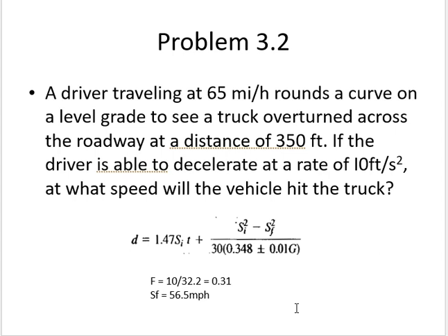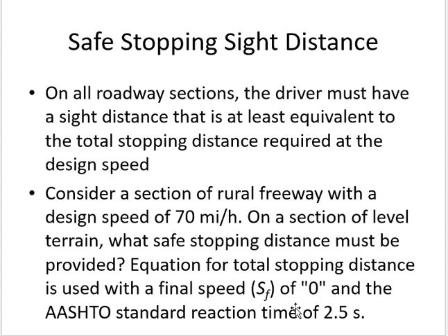to calculate how much distance the driver needs to stop. Since we are doing the design, you can keep the value as it is, 0.34. The perception reaction time is 2.5. Finally, the final speed will be how much? 0, because we are talking about stopping, right? So this equation will tell you how much visibility should be maintained on this highway. Clear? Any questions?